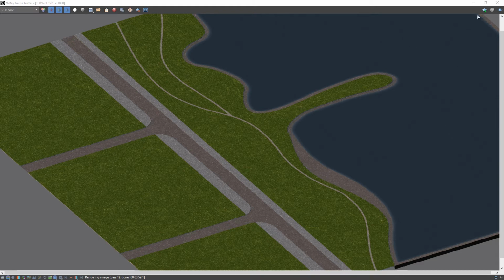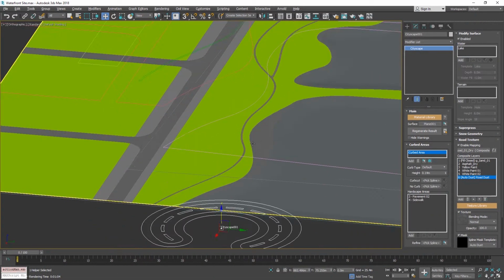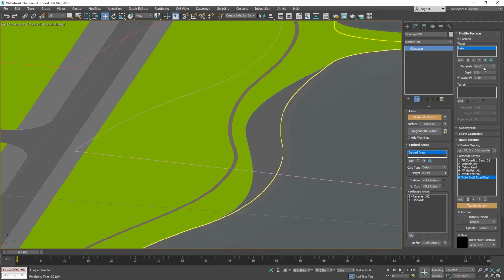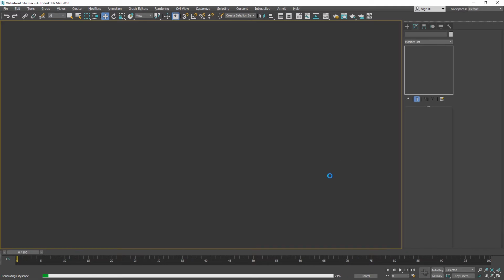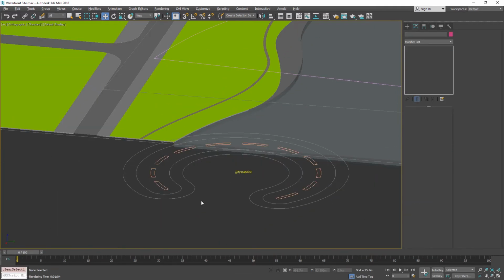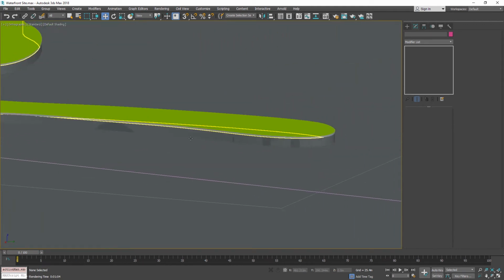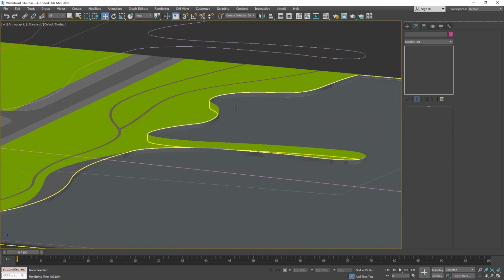And again, if you'd like to have more control over the waterfront area, you can always switch back to reservoir template, generate. Then you can just create a custom beach geometry, whatever necessary. You can also use some kind of scattering tool to scatter rocks around the edges.